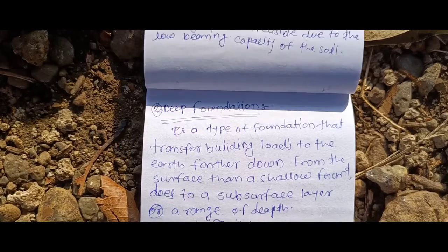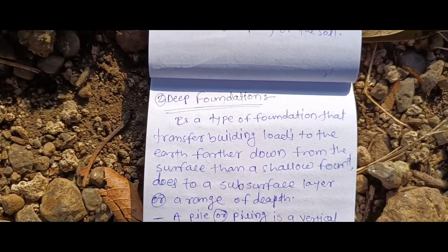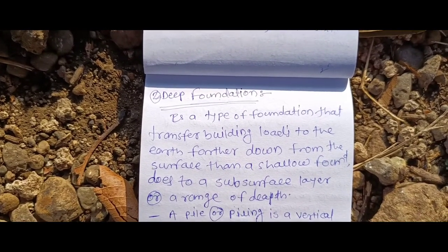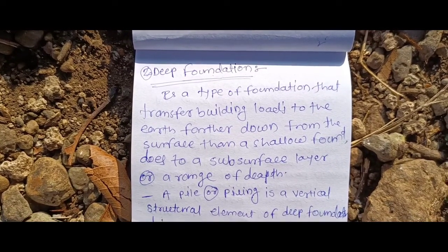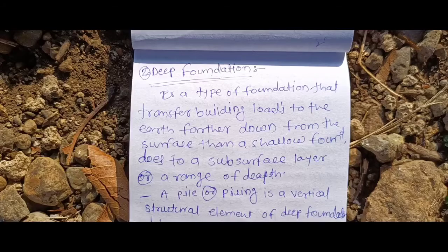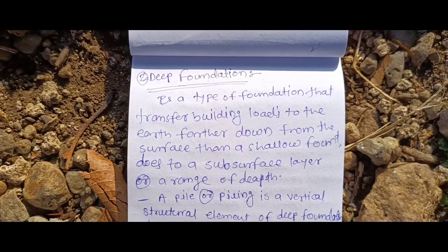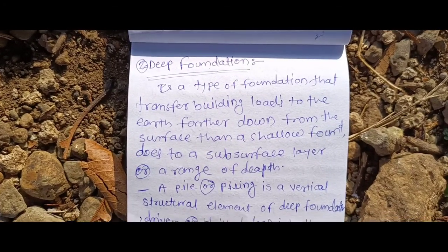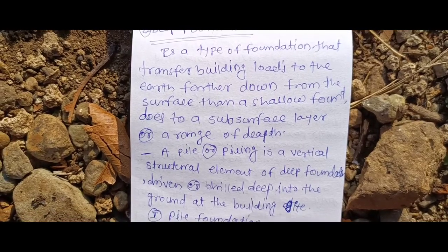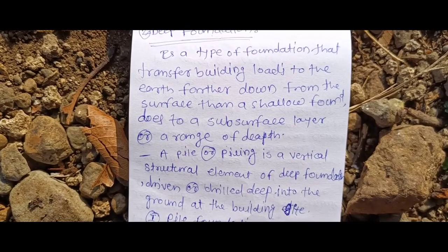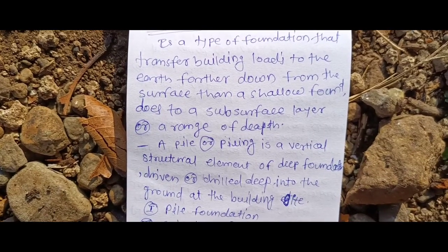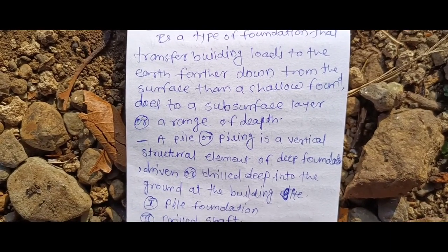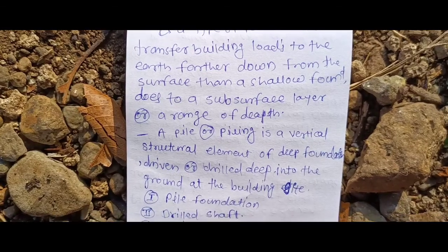What is deep foundation? Deep foundation is a type of foundation that transfers building loads to the earth further down from the surface than a shallow foundation does, to a subsurface layer or range of depth. First point, a pile or piling is a vertical structural element of a deep foundation driven or drilled deep into the ground at the building site.